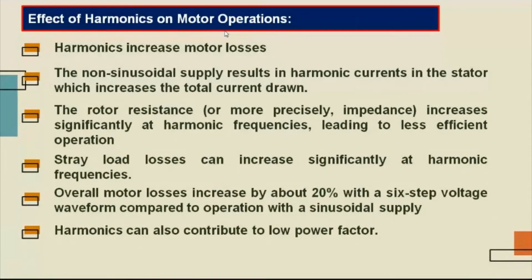So harmonics increase the motor losses. If the harmonics increase in the motor operation, then the losses in the motor will increase. And if the losses increase, you all know that there will be an overall effect on the efficiency of the motor. So that's why the effect of harmonics on the motor is also an important parameter which should be known, and there should be sufficient mitigation or elimination of these harmonics on the motor terminals.